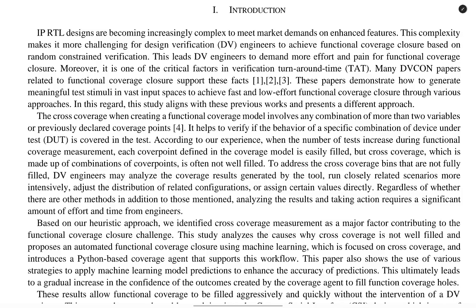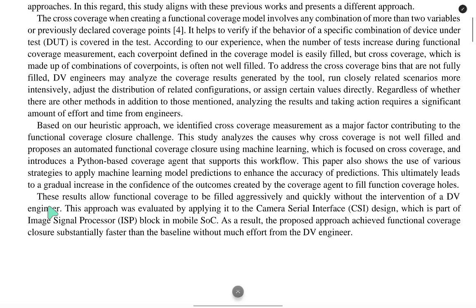fully filled, the DV engineers may analyze the coverage results generated by the tool, run closely related scenarios more intensively, adjust the distribution of related configurations, or assign certain values directly. Regardless of whether there are other methods in addition to those mentioned, analyzing the results and taking actions requires a significant amount of effort and time from engineers. Based on our heuristic approach, we identified cross coverage measurement [2] as a major factor contributing to the functional coverage closure challenge.